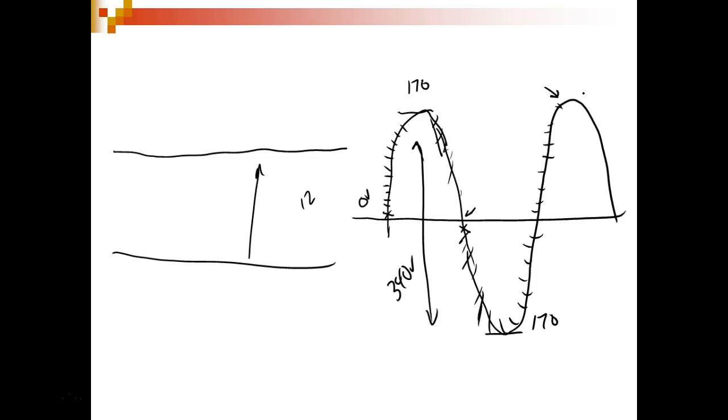People shouldn't call it an average voltage. It's an effective voltage, and this is how much work a resistive load will do. So if I had 120 volts RMS across a resistor, it would do the exact same work as 120 volts DC.